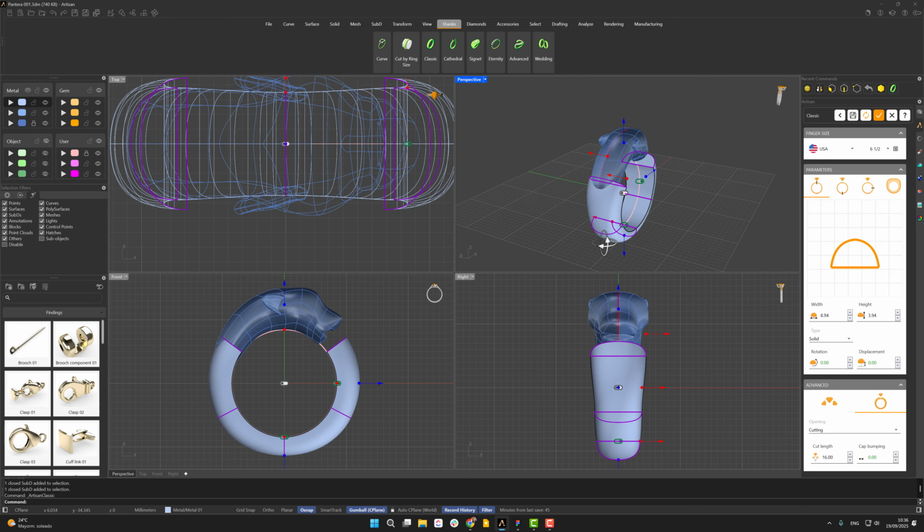Hide the original. If you see that the union is not completely smooth, you can do 2 things: adjust better and unite everything again, or adjust the resulting Sub D. You can delete edges to get a smoother result. Remember, the organic model must be to your taste.